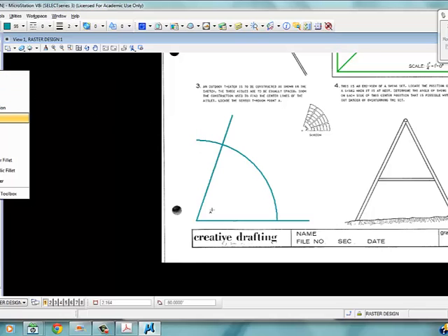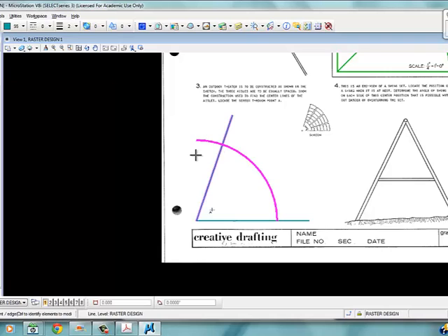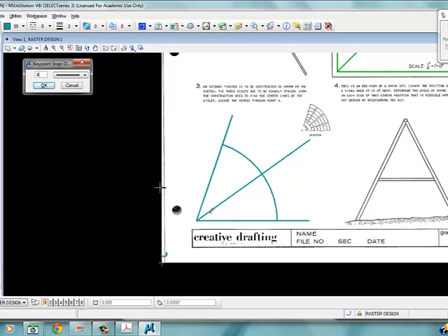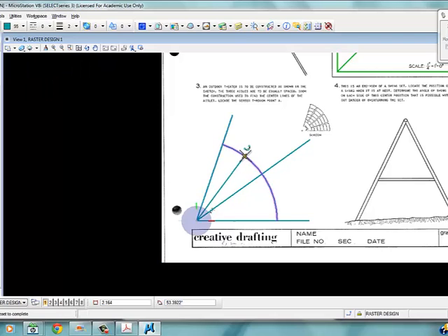Let's trim this 7.5 to this angle, so that separates our arc. And let's find the divisor right down the middle first. There's our center point. So there's this aisle right here. Now we need to find these two. We could break the line into 2 separate pieces, but let's do a spacebar K, and we'll change this to 4 segments. So now we can find this divisor and this divisor. So now we have our 4 sections.